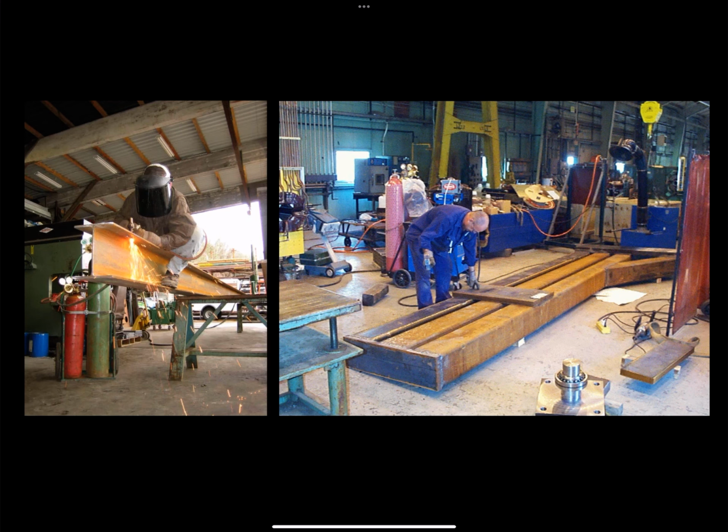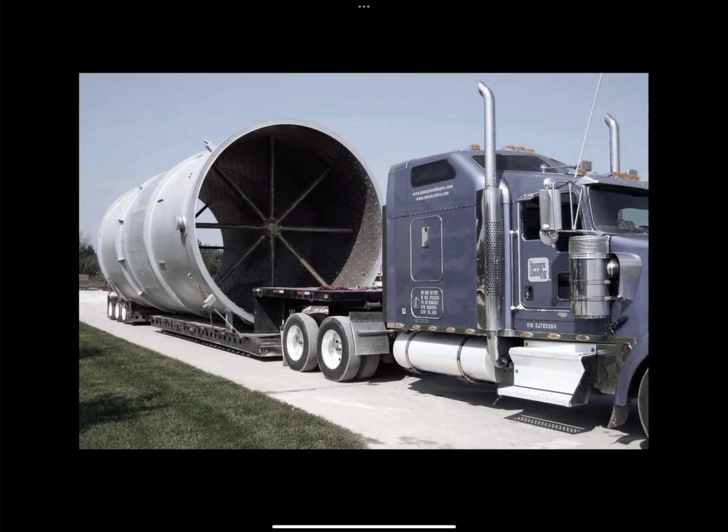And the limit to the size of elements that can be prefabricated is determined by the method of transportation from the workshop to the building site. And so if you're transporting by truck, you obviously have rules about maximum sizes of loads on the highway. If you're transporting by ship or by train, you will have different dimensional constraints to work to.